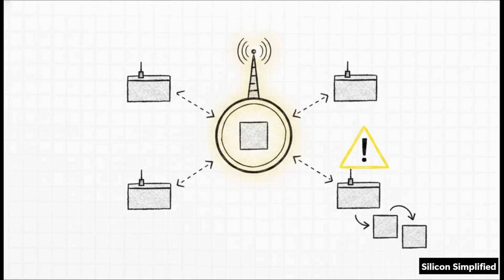So the crucial takeaway regarding analysis ports is that they are specialized for one-to-many non-blocking broadcasts. They use a single, specific void function called write. Because write is a function, it executes instantly in 0 simulation time. This means a monitor can broadcast a transaction to 5 different subscribers, and its execution thread will literally never block, no matter how long the subscribers take to process the data.